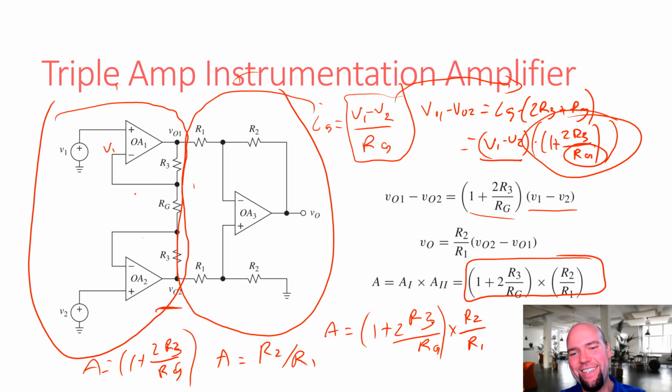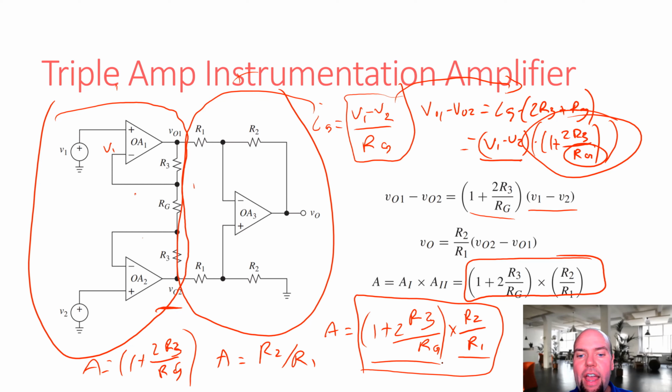Okay, you got it. All right, now that's pretty cool. So now we have a differential input amplifier that has ideally infinite input resistance, and it has a gain that's given by this. The cool thing is we have 2 stages of this amplifier. We have 1 stage gain here and 1 stage gain here, and a single resistor will change this gain stage. Neat.